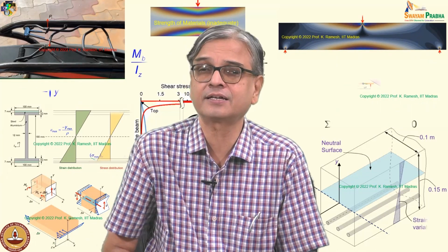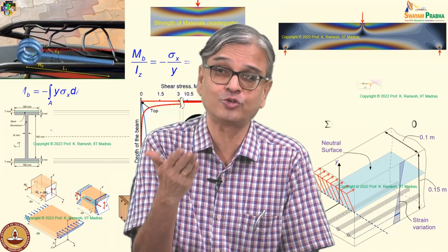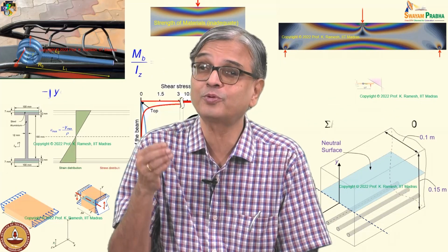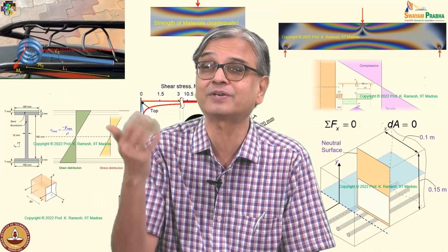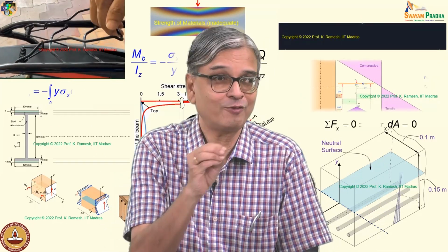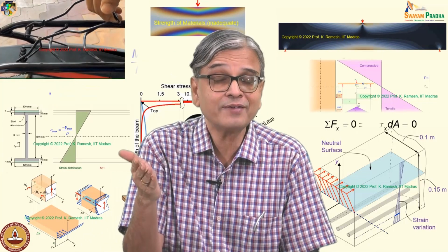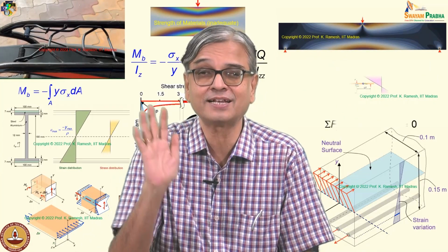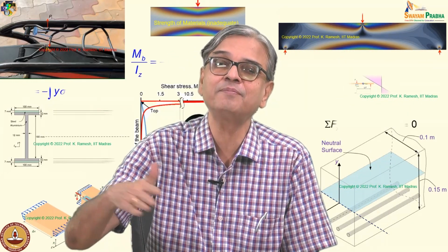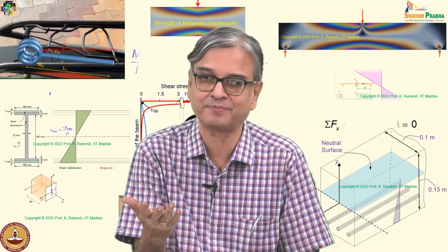Then we have also looked at how to reinforce a concrete beam. One of the very important applications is that you should know the bending moment diagram, so that you find out which is the tension side and which is the compressive side. You should not put the steel bars on the compressive side and say that you have reinforced the beam. The whole building will collapse. I also narrated one instance where somebody made a concrete beam without putting in any reinforcement. Suppose somebody has made a mistake and you have to do retrofitting. What can I do? I can bond a steel beam firmly on the tension side. That is one way of alleviating the problem.